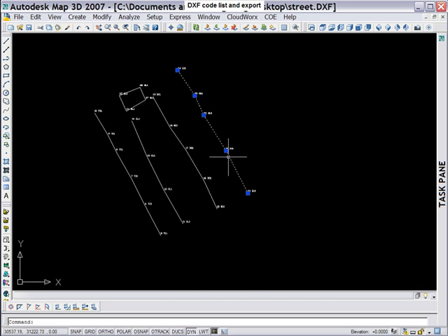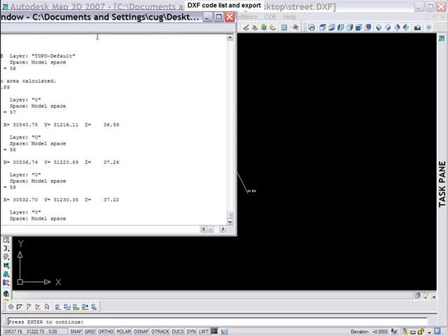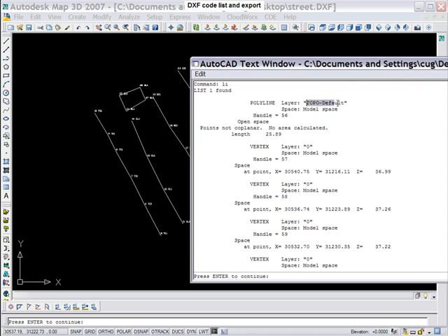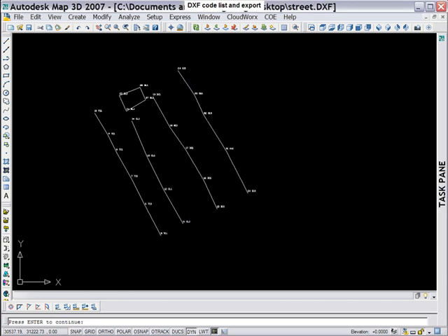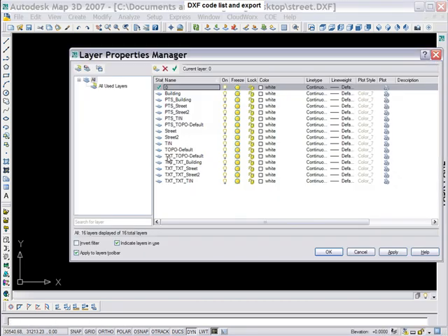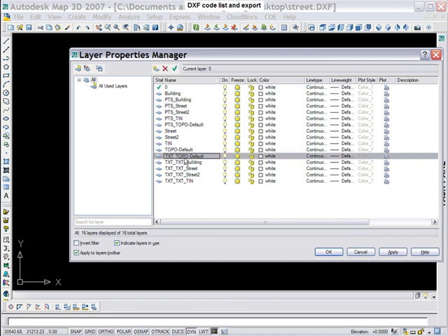The gutter line here is in the layer called Topo Default. Okay? So if you do not put down any layer name when you're creating your text file for importation, and you just lay out lines and then export DXF, it'll import into AutoCAD using the default. So here's the default layer name: Topo Default. So it tells you those are using default names.